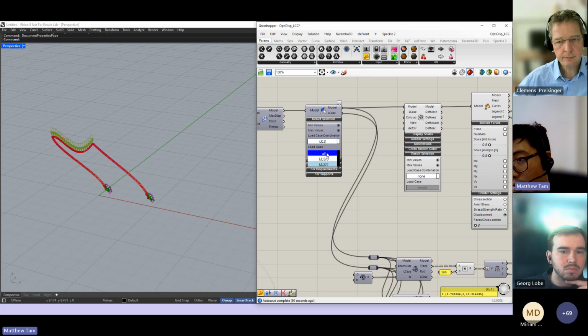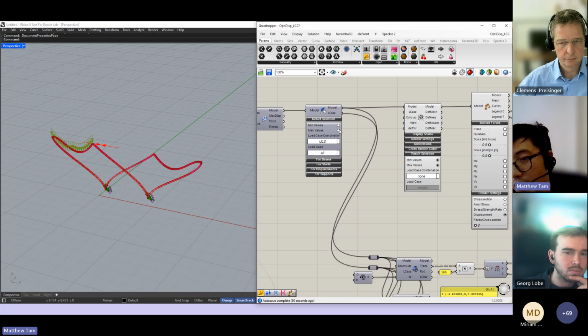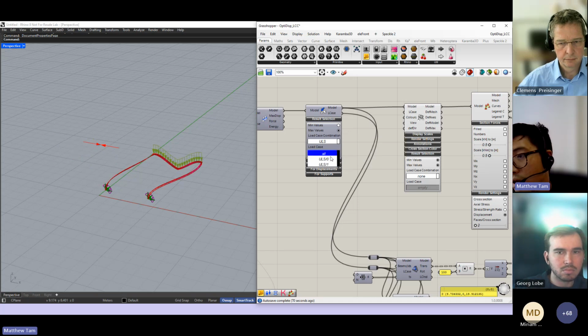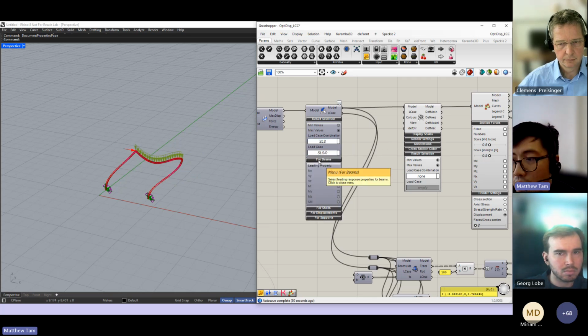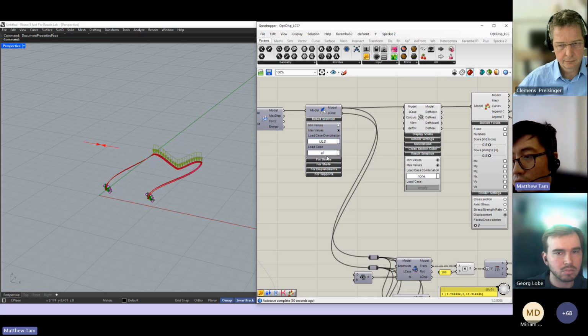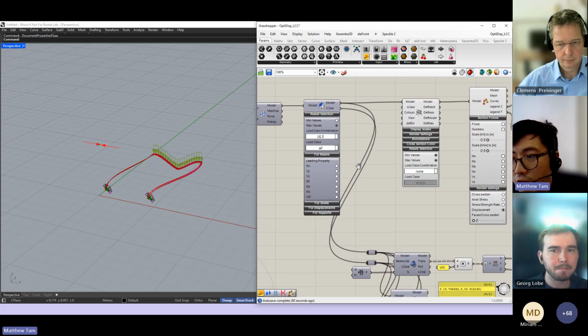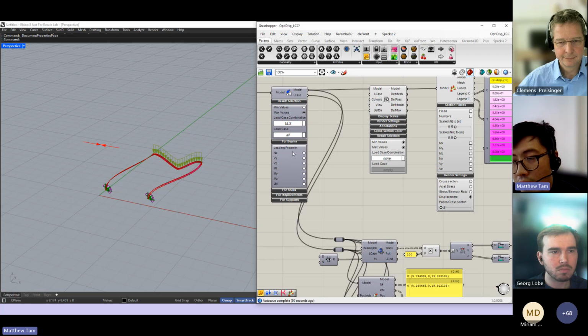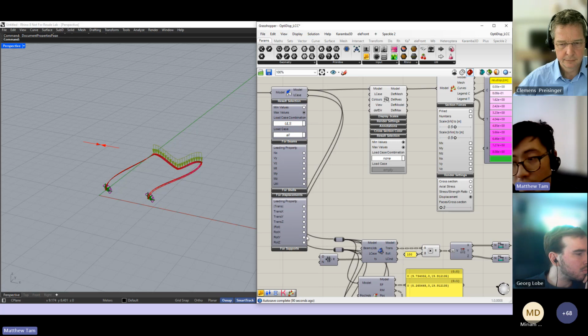If we go to OR, for example, we can select if we want to preview the minimum or the maximum value for all ULS combinations. And here you can also filter through all the subsequent different load cases or load combinations too. If there are multiple load combinations, you can also filter them with the leading properties, for example, based on normal forces, bending moments, or if you were interested in looking at displacements or even the supports.